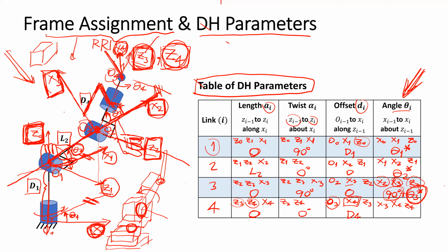Theta 4 can create some angle difference between X3 and X4 in any possible direction that is perpendicular to C4 and passes through O4. So we can control the angle of theta 4. Now we have all the parameters of the links from the Denavit-Hartenberg notation.